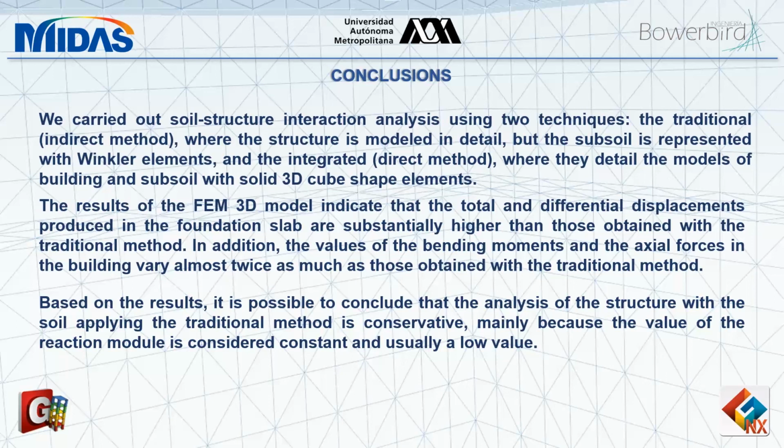We saw that the 3D FEM model with the soils in solid shapes indicates that the settlements, total and differential, are higher relative to the traditional method, as well as the bending moments and the actual forces, which are over twice what we were getting from our structural point of view.